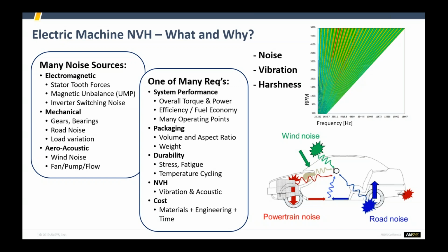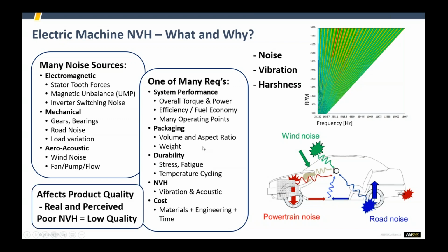The forces causing these vibrations can come from many sources. For electric machines, these may be magnetic forces that act to turn the rotor shaft, or they could be part of the larger drive system, such as from the bearings and or the gears. So a lot of the sources, and of many requirements, one is for system performance, one is for packaging, one is for durability, and NVH is considered, and lastly as well the cost.